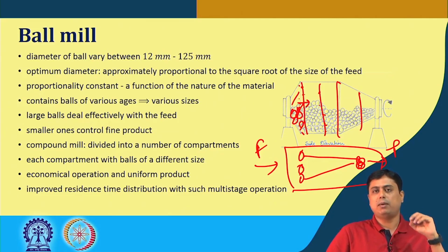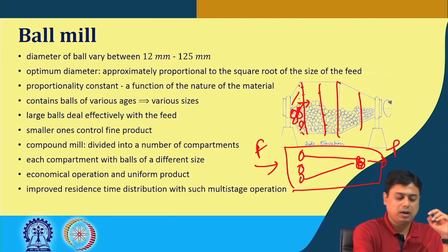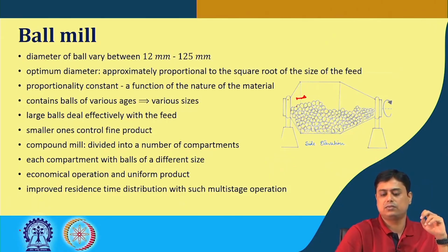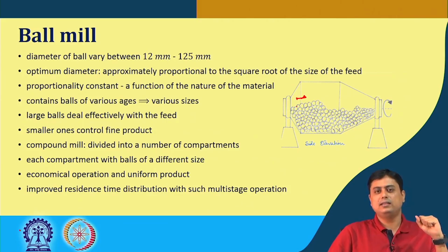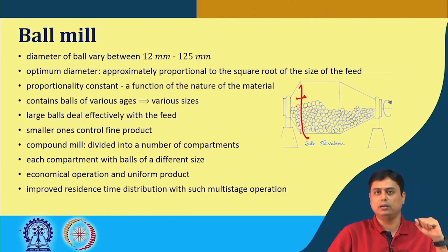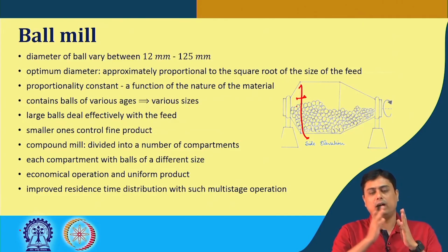So, the particles that have been crushed in this chamber, or say the coarser particles, if that size is not that of the screen size or lower, cannot pass through and would be retained in compartment 1 until that size is obtained. And by doing so, we can have a uniform product and size distribution.